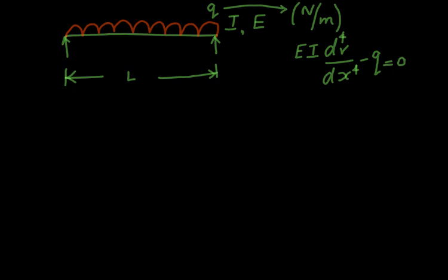Okay, where E is Young's modulus, I is moment of inertia, v here stands for vertical deflection, transverse deflection. x is any arbitrary location on the beam measured, reckoned from the left extreme end. So that is x. It may point at the center of the beam or any position on the beam, any arbitrary location on the beam. q, you know, is the rate of loading.